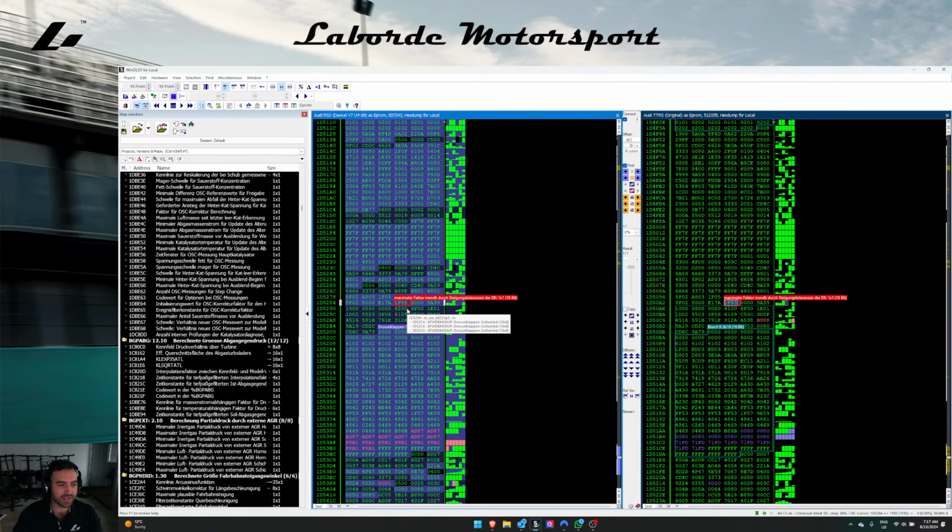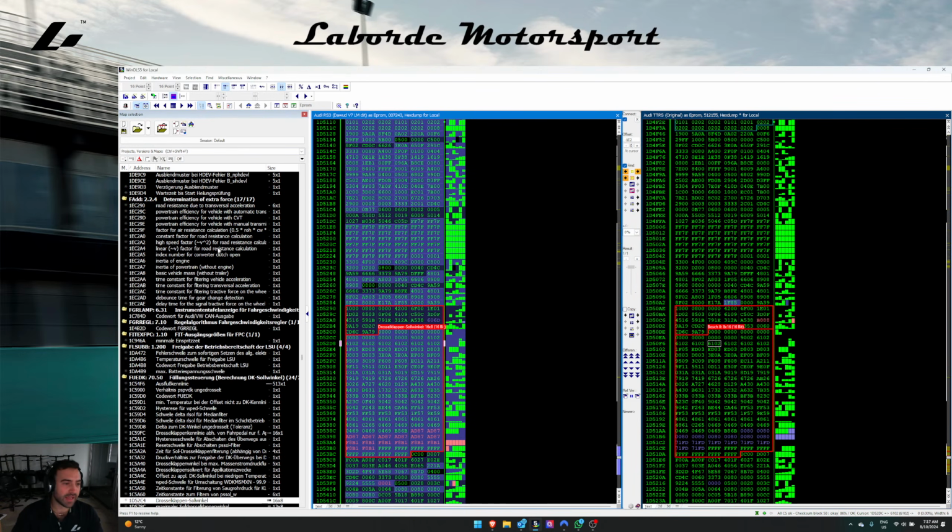That does mean that technically it won't work within a closed loop boost pressure control system. However, this particular ECU and car is on a very big turbocharger, so it'll be open loop anyway based on pedal position and engine speed. There's no closed loop control system for this car. We'll be reading the boost pressure externally and the ECU won't be doing any of the boost pressure control. We just need to allow it to go over the internal 8-bit variable limit of 255 kPa so that we can have full power. So nevertheless, we're going to get straight into it.